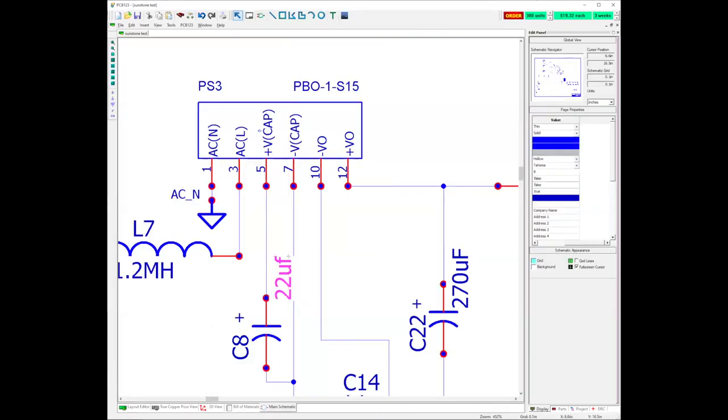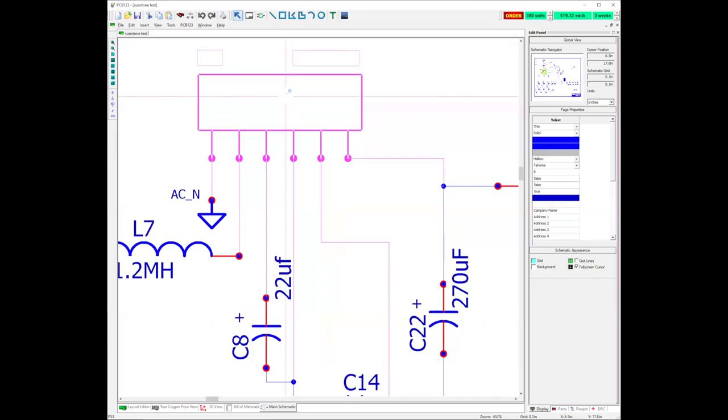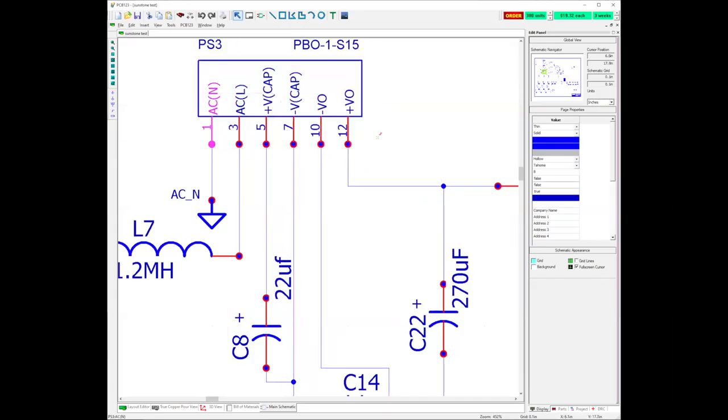So when you're moving, just be real careful when you move a part that has more than a couple of pins, that if you move it sideways or across the pins like so, this direction versus just stretching wires, that you don't end up with a wire from pin to pin. Anytime you see that on your schematic, it's probably a mistake. You probably didn't do that on purpose, and it's going to be very difficult to fix.